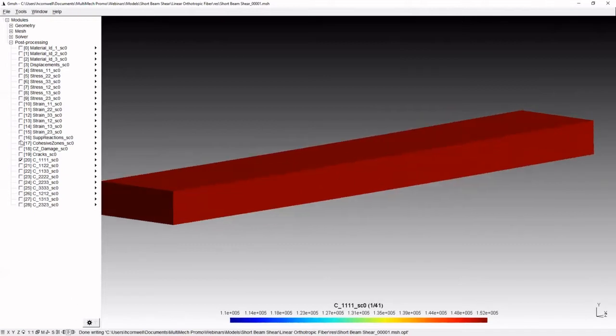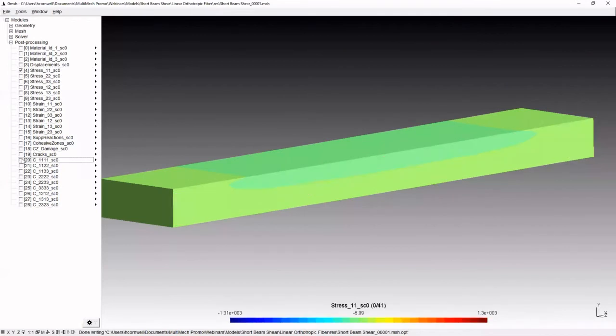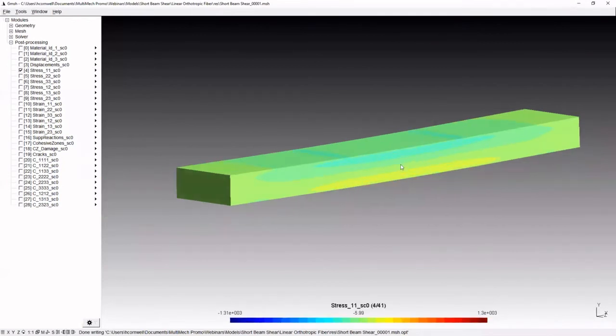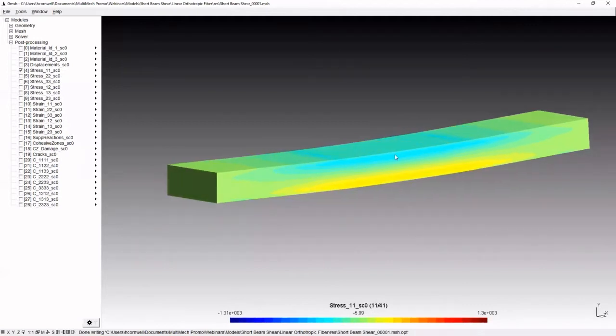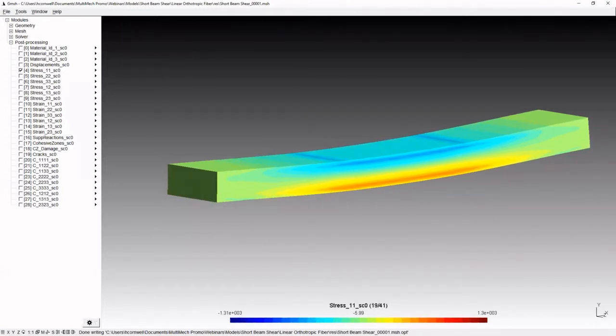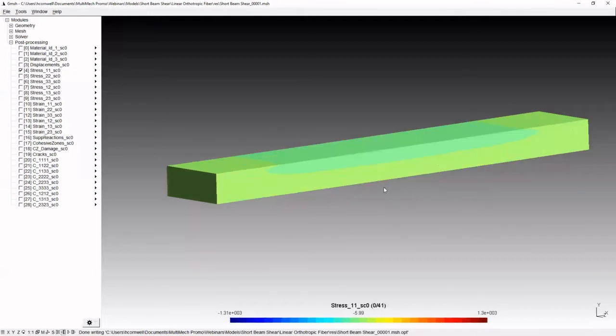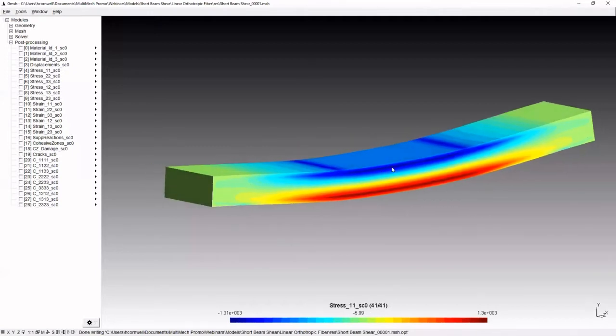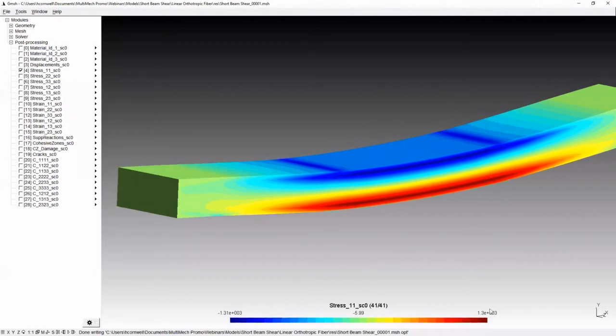And this is translated over to the stresses. When we run the loading and look at the stress in the one direction, we can see compression in the top and tension at the bottom. We notice that at the maximum, when we finally get to the last load step shown here, we have pretty much even tension and compression because the modulus is perfectly linear elastic.